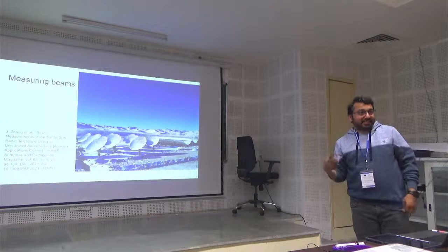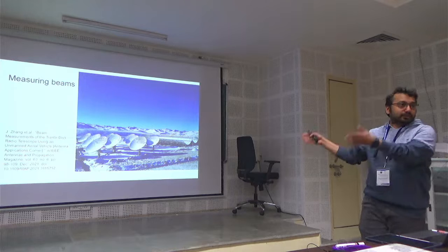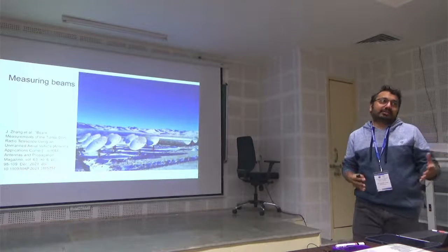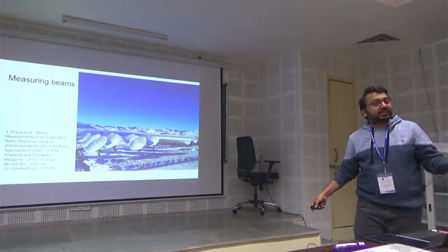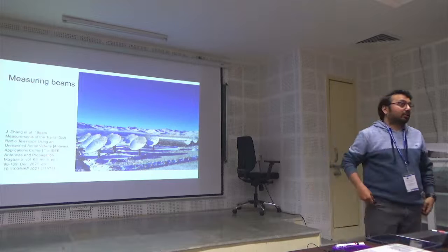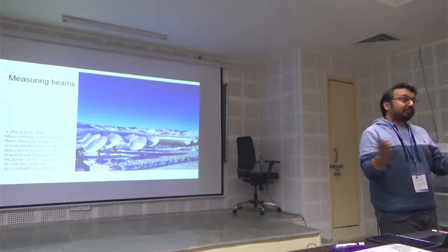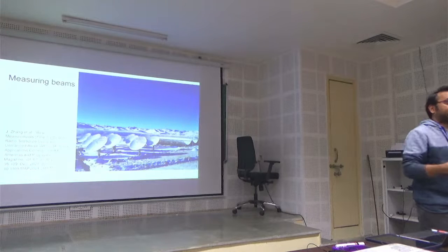So this is instructive, but ideally the way you would want to measure it is in situ. You have to be in that embedded location and then measure it. That's the real thing, because then it also talks to other antennas and that influences its radiation pattern. Because as you rightly said, these are all in the near field, not in the far field at all. So these two things can be very different. I can show you a paper later where these things have been compared.